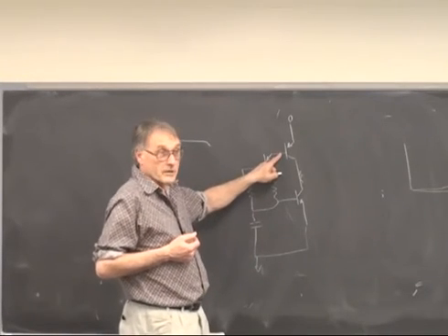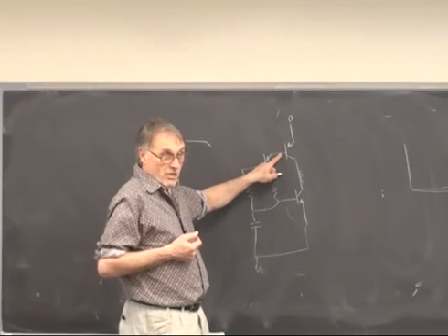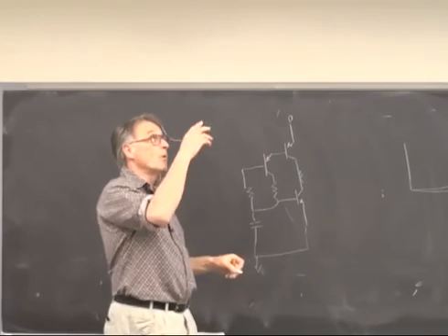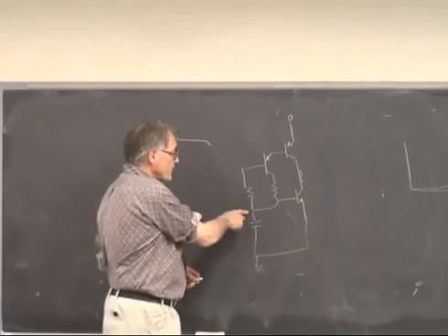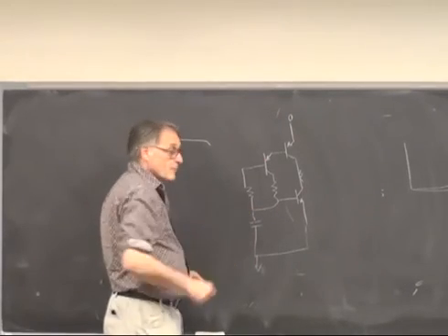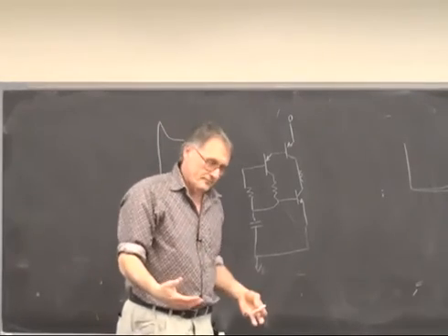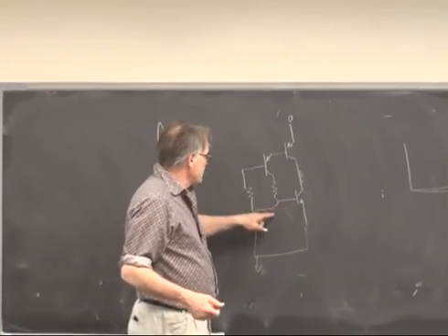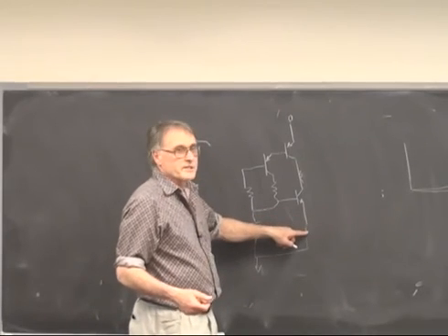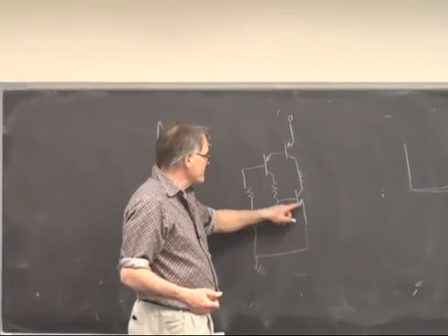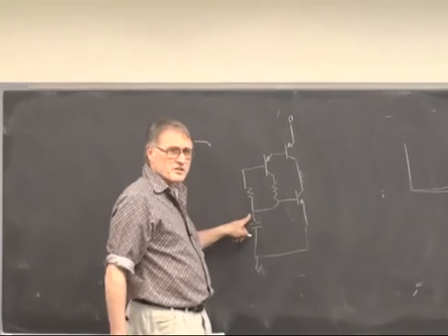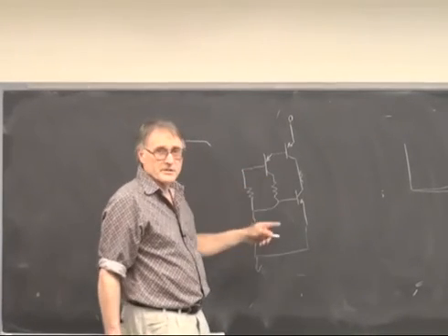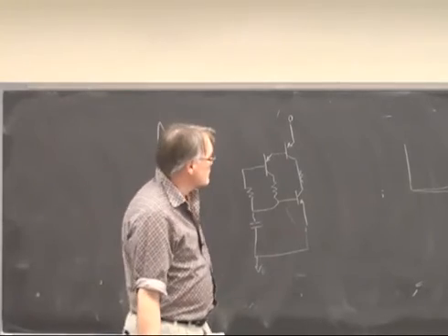This transistor is going to cut off because it is no longer 1.4 volts more negative than this voltage here. This voltage falls enough for the transistor to turn off. Once this transistor is turned off, there's not much place for this charge to go, and it just stays there. It actually slowly leaks out through various leakage paths.